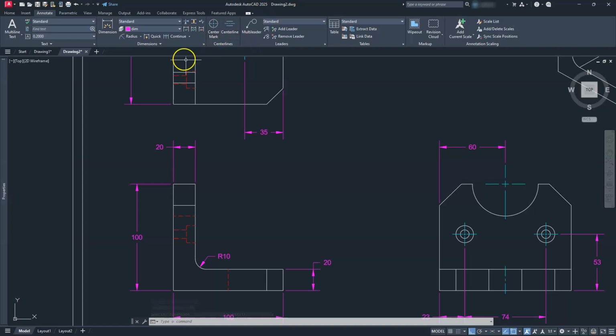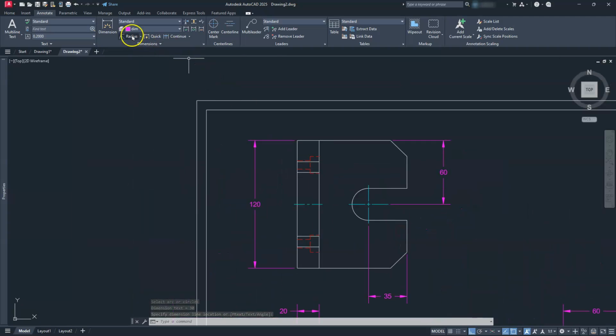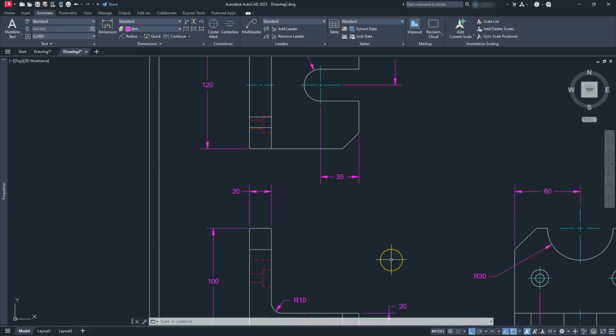We do have another radius dimension, and it's located here. And let's put the one that's located here at the top. Okay. And now for the last step I need, these are going to be leaders. So I can set up quick leaders for these, but it's going to be a lot simpler for me to use multi-leaders for these. But I'm just going to show you a quick leader, since I don't think we've ever discussed quick leaders too much on here, right?